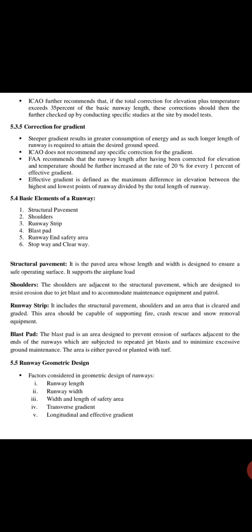Effective gradient is defined as the maximum difference in elevation between the highest and the lowest points of the runway divided by the total length of the runway. Basic elements of the runway are structural pavements, shoulders, runway strips, blast pad, runway end safety areas, stopway or clearway.